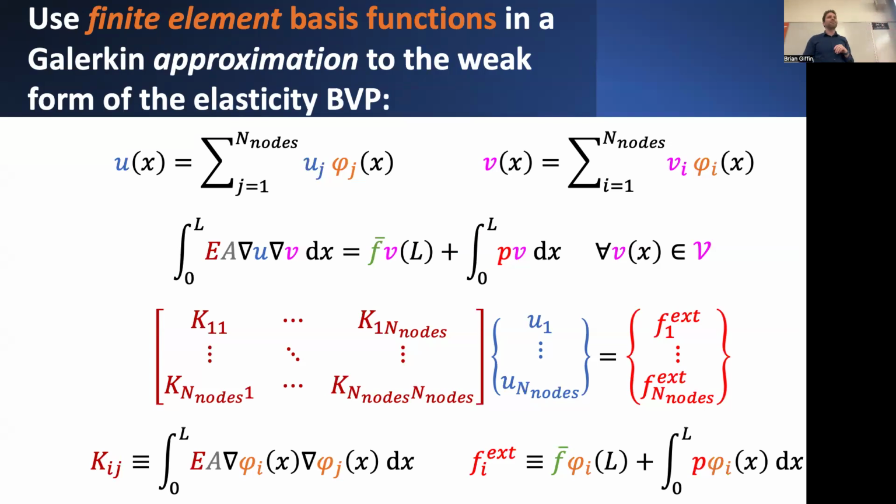We could also come up with an expression for some arbitrarily chosen test function, or if you like, this test function could be interpreted as a virtual displacement field, which has a similar representation expressed in terms of these discrete virtual nodal displacements, the v sub i's, and also expressed as this kind of linear combination of the finite element basis functions, the same set of basis functions.